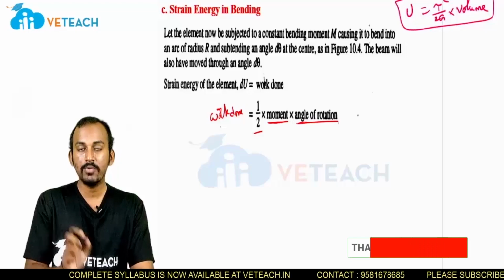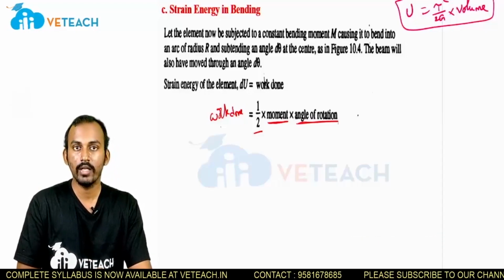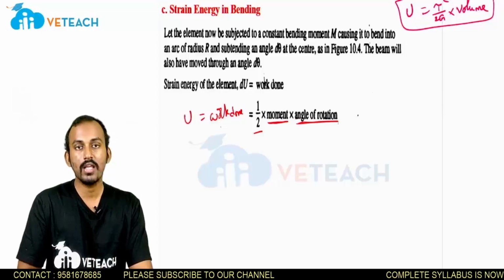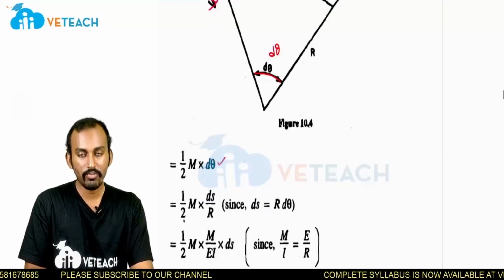Okay, that means the member has been rotated. So half into moment into rotation, that is the work done. Work done means nothing but the strain energy. So now, half into M into d theta. This is the formula for the strain energy.